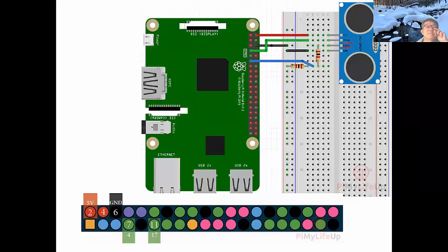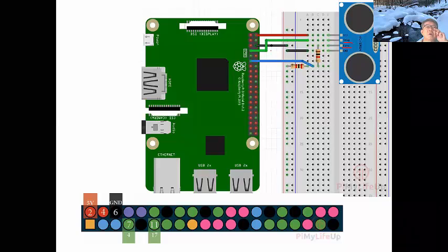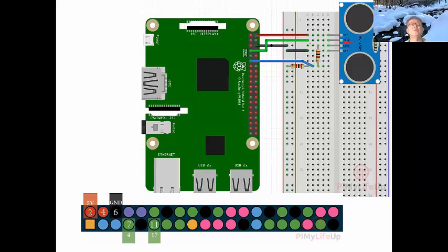And there's some resistance, and this low power, but particularly for this ultrasonic sensor, you don't need this, okay? So we're not going to use this. We're not going to use this, okay? So you can practice without it, that's fine. You simply connect ground, power, and whatever the pin number that you want to use, simply connect it. So you don't need this breadboard, actually. That's what I'm going to show to you, okay? That is distance detection.